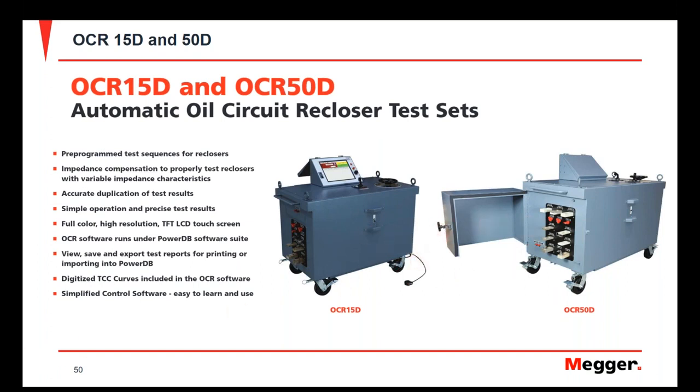What both instruments are going to provide for you is pre-programmed test sequences to help you do those performance tests on the reclosers like we talked about earlier. They also have the ability to have impedance compensation to help overcome the influence of variable impedance that can happen with some reclosers.